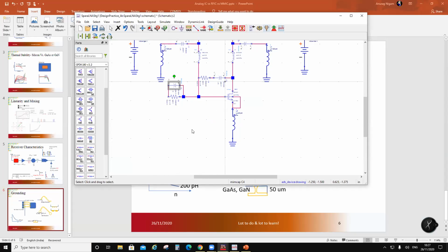If you buy what they call the power bar, it comes only with the resistors. What about this cap? You are killing the gain. You have to kill the gain at low frequency, not at the high frequency. So for high frequency, give a bypass path.